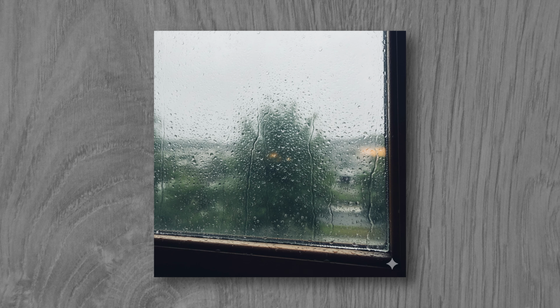One of the primary reasons modern buildings experience more window condensation is their enhanced insulation and airtight construction. Older buildings often had natural air leaks through cracks, gaps, and less efficient materials, allowing moisture to escape more freely. In contrast, modern energy-efficient buildings are designed to retain heat, which also traps moisture indoors. The higher indoor humidity increases the likelihood of condensation forming on cold surfaces, such as windows.